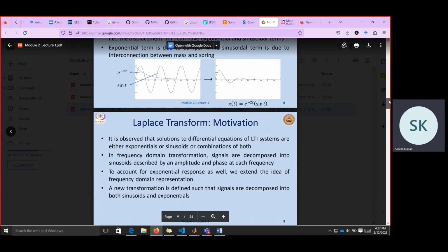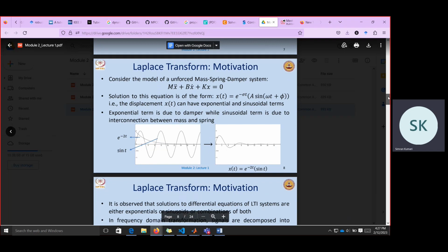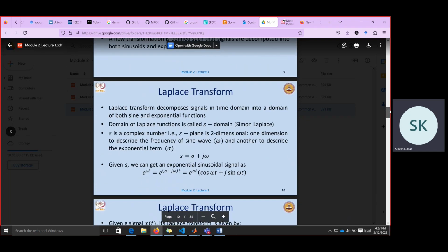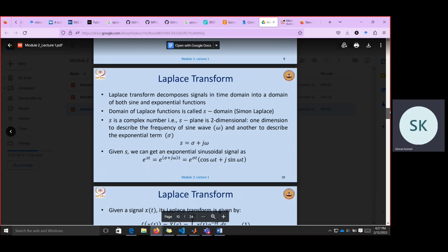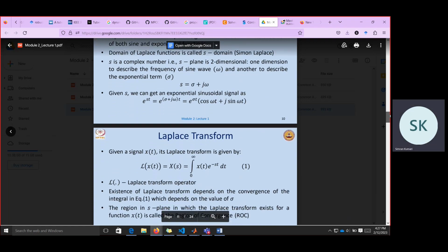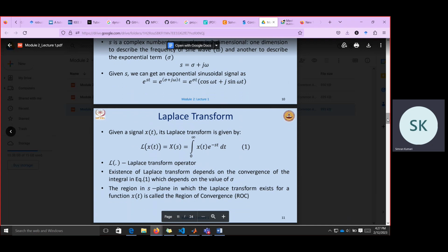Okay, so this is what sir has explained, giving the motivation for the Laplace transform. Basically now we are adding a real axis to the S domain. And later on you will also see how system stability or causality can be explained using this transfer function. If the ROC contains the imaginary axis, then we can say the Fourier transform exists, or that the absolute sum of the impulse response converges. So this is a stable system.